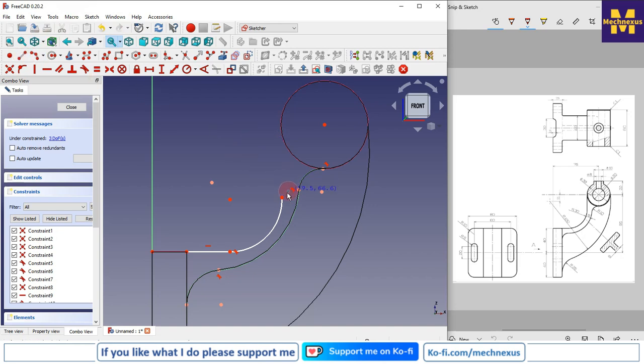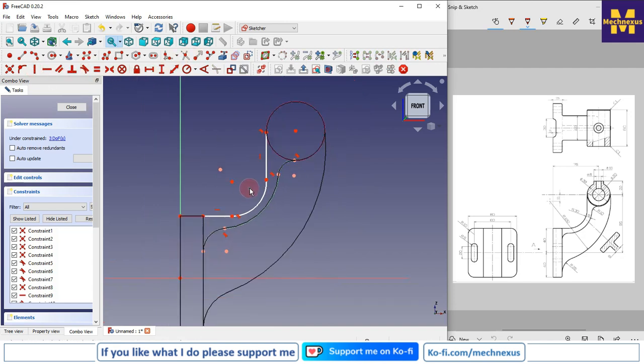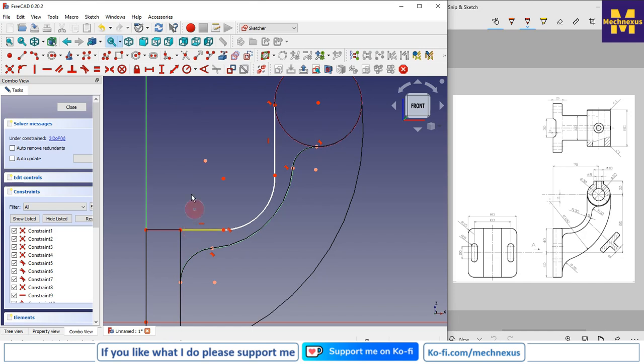draw a line and make it tangent, and also I will make it vertical. And this radius is R30, so I will give it 30, and here I will give the tangent relation.